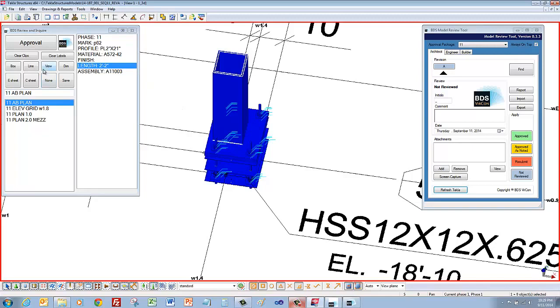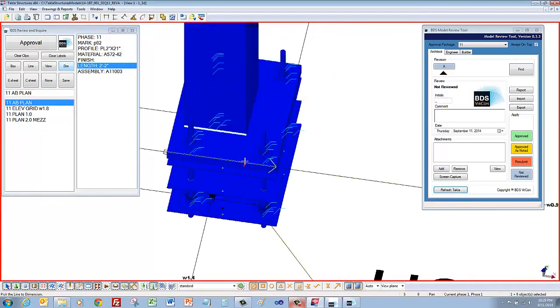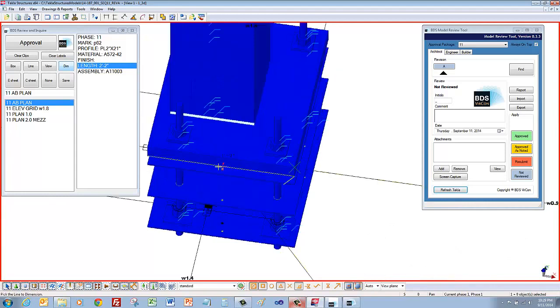What we can also do is we can press the dim button, which will then activate us to select a line here in the model and provides dimensions. The dimensions can be selected by this line by making sure that we have these snap to geometry lines and points snap here on our toolbar, as well as we're selecting objects and components here in the model.